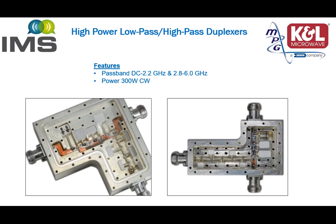For powers in the magnitude of hundreds of watts, special high-pass, low-pass duplexers are designed. In this example, we have a low pass from DC to 2.2 GHz and a high pass from 2.8 to 6 GHz with power handling of 300 watts CW.